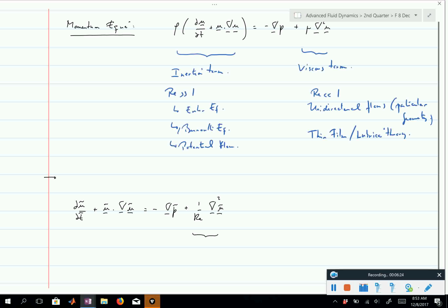You know, when we discuss lift, for instance, we discussed lift for inviscid flows, but we did mention that the reason why you impose the Kutta condition is because in reality there are effects of viscosity. Right? You do not expect the flow to be able to infinitely move around a sharp edge at the trailing edge. And because there are effects of viscosity, because you know that if you sharply turn around the corner, there will be enormous shear.